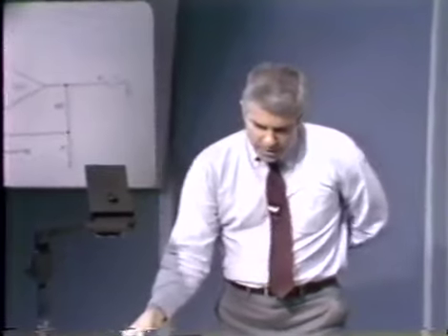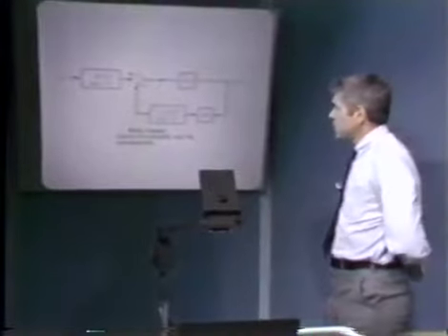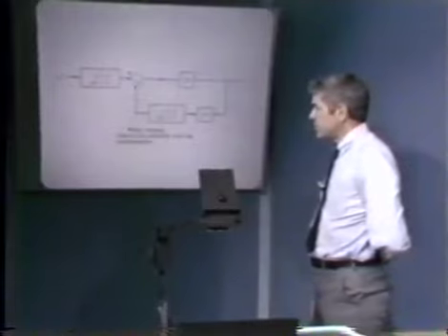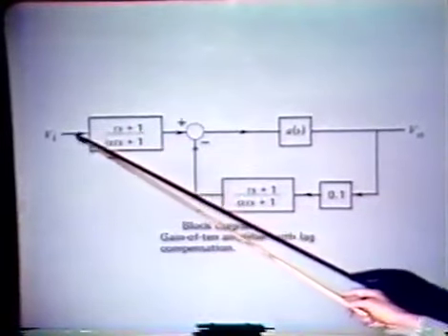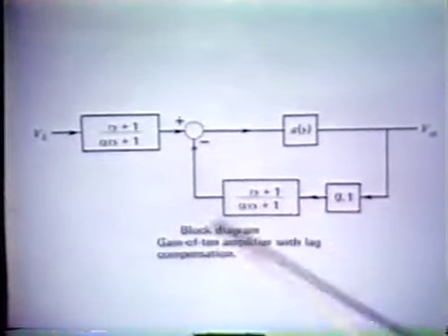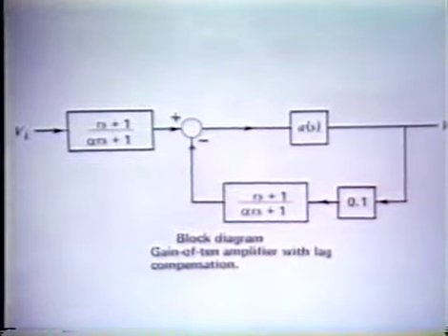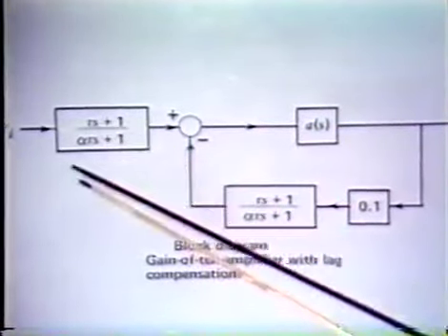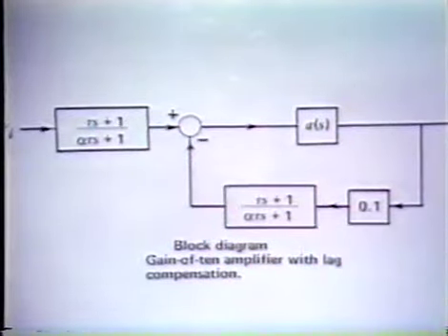The effect on the block diagram for the amplifier is as follows. This again parallels very closely what we did in an example, I believe 2 sessions ago, where we put a resistor between the terminals. We found out that that resistor provided an attenuation to the input signal as well as to the signal fed back. Here, because we use an RC between the input terminals, we get an attenuation or a lag type transfer function applied to both the input signal path and the feedback signal path.